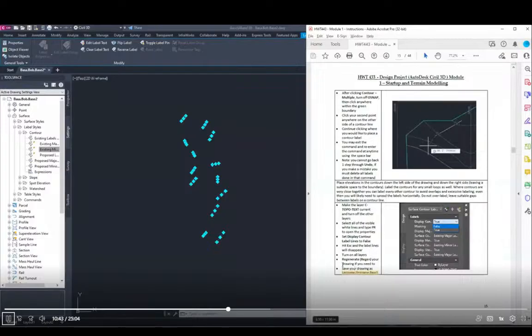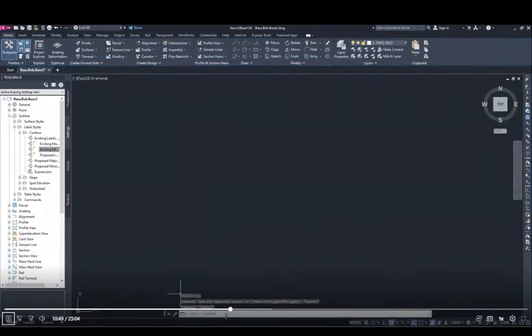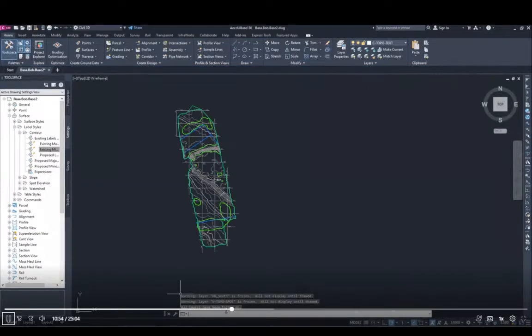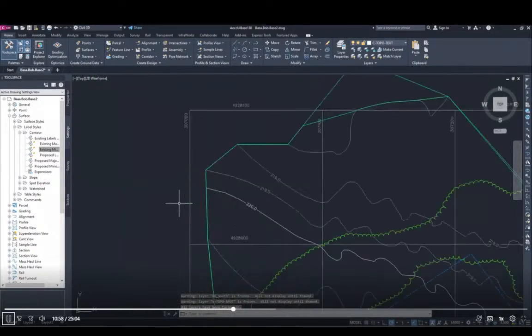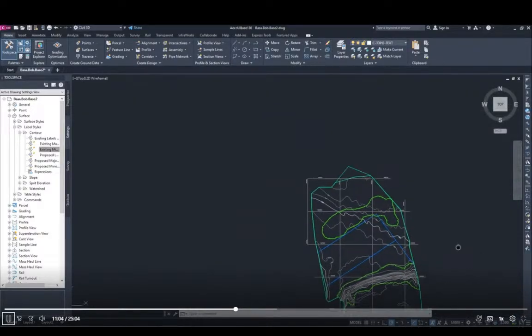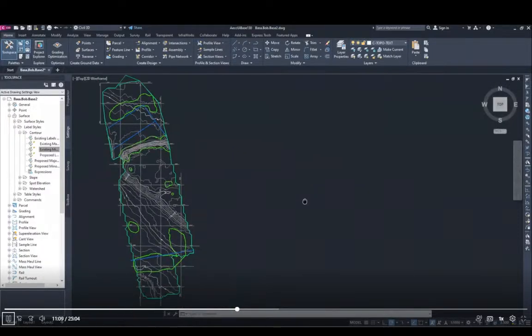There we go. We are going to turn on all the layers again. We're going to, first of all, unselect here so it doesn't show anything. And then we're going to do lay on, turn on all the layers again. There we go. So what we did there is, if I zoom in here, remember those contour lines? Now the elevation's there, but that line that we drew is no longer there. We just kind of removed that from the drawing. Let's just bring that into play there.